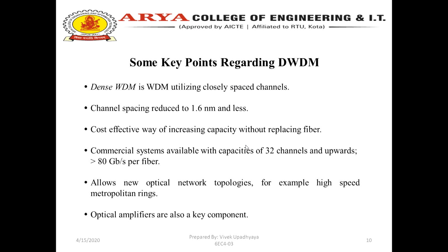Some key points regarding DWDM. Dense wavelength division multiplexing is WDM utilizing closely spaced channels. The channel spacing is reduced to 1.6 nanometers and less. It is a cost-effective way of increasing capacity without replacing the fiber.